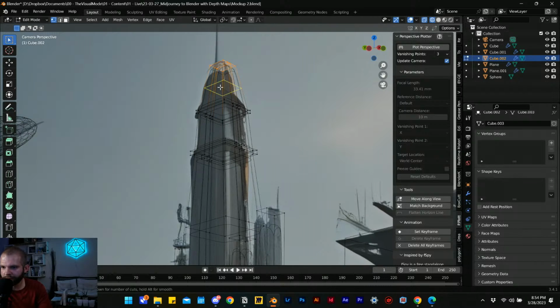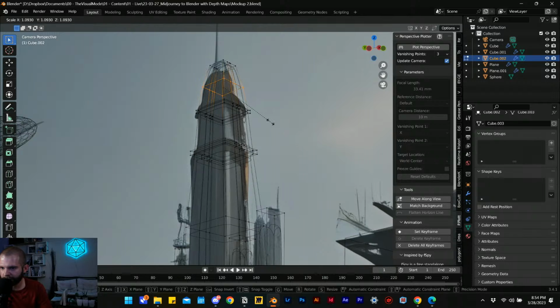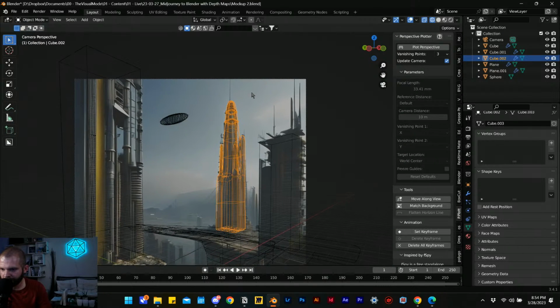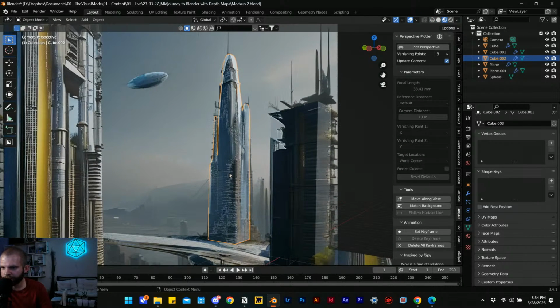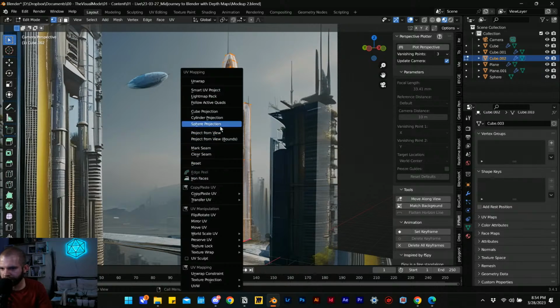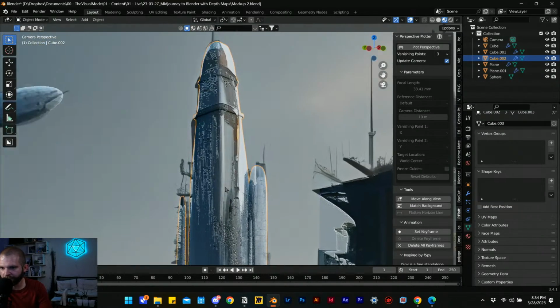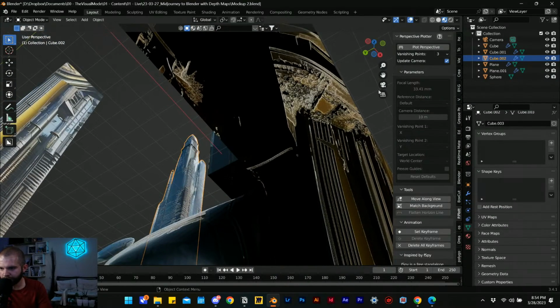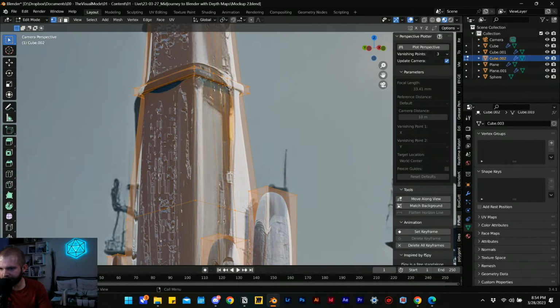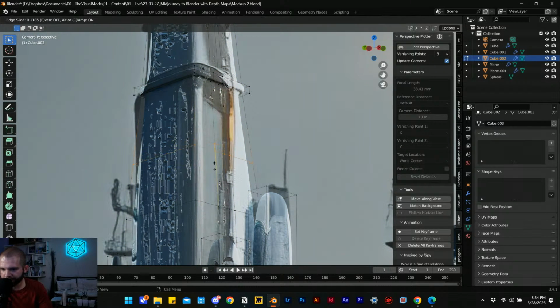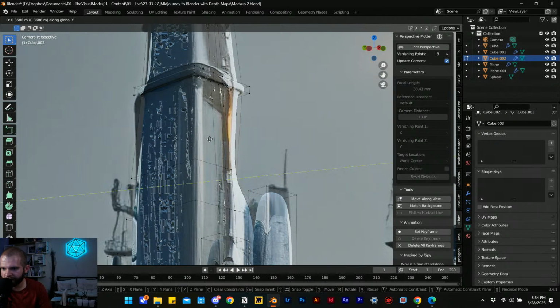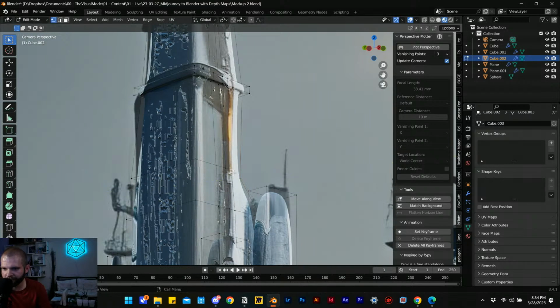Okay, and another loop cut here, that a bit larger. Okay, material preview, AU, project from view. There we go. So yeah, the more cuts, the more details you're able to add into the model, the better the image will end up fitting to the geometry every time you refit or reproject that geometry or that image.